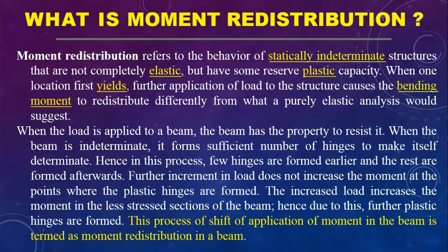When one location yields first, further application of load to the structure causes the bending moment to redistribute differently from what a purely elastic analysis would suggest.